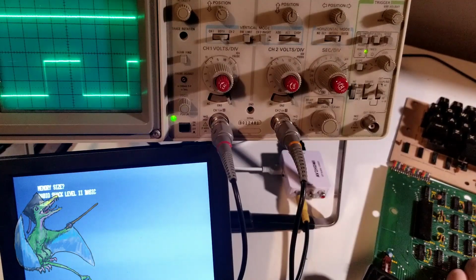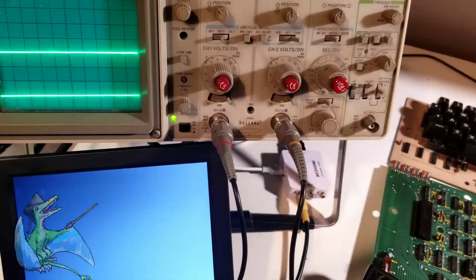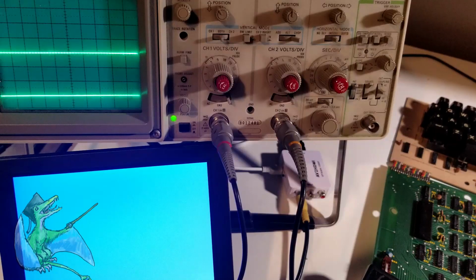Okay, so I guess the question is, should I just go ahead and desolder that? Or I'm thinking, let me try, so that is like pin sharp. Let me try a different value. Let's go a little bigger. We don't want to put too much capacitance on it. We also don't want too little. So this is a 331 I'm going to stick in here.